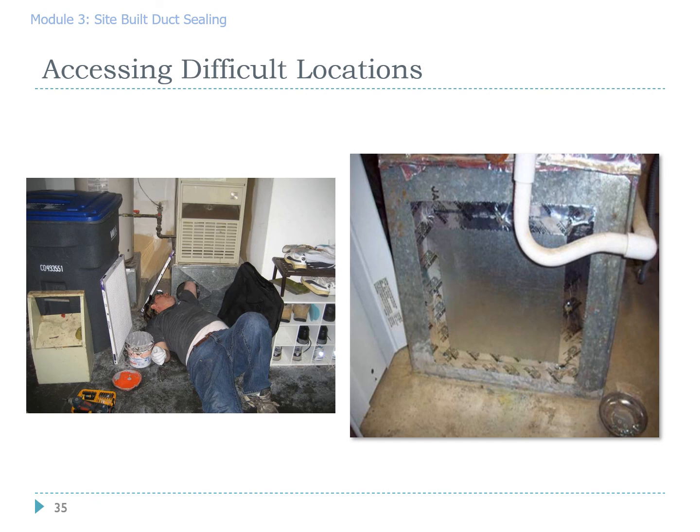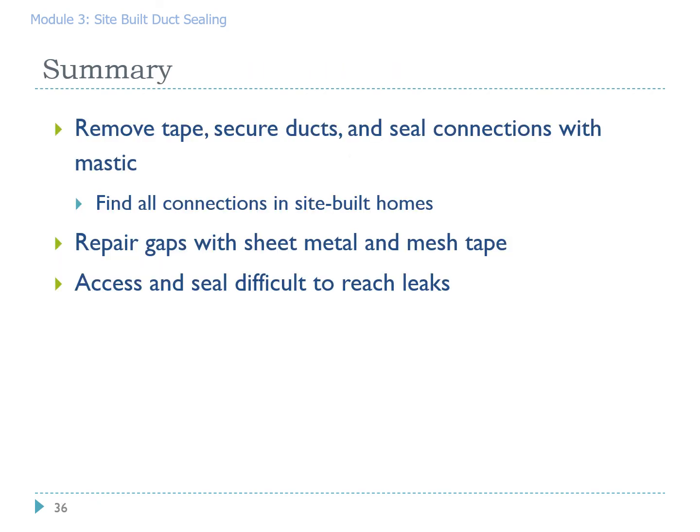What you can't see in the picture is that he actually covered this hole with some duct tape so there are no sharp edges that he was going to put his arm into and potentially get cut on. When he was finished, he boilerplated a piece of sheet metal over the hole. He carefully attached the duct liner also and covered the whole thing after he screwed it on with some nice UL approved metal tape.